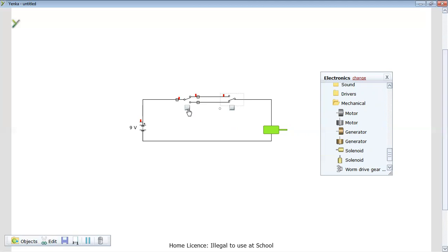I'm only activating one switch to make the circuit work. So this is literally just the one valve I'm pressing. So the OR circuit has those two on there, but you only need to press one. And I can go over here and change that as well. I can even flick backwards between the two of them. Now, this particular layout works for a number of different things. You might have somewhere in your house, I'm sure, a light that is operated by two separate switches. And it doesn't matter which switch you turn on, it will activate that light. This is the same principle. So I can even take this here, I can delete that.